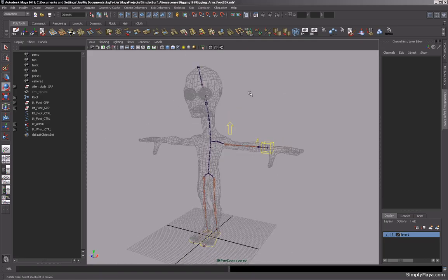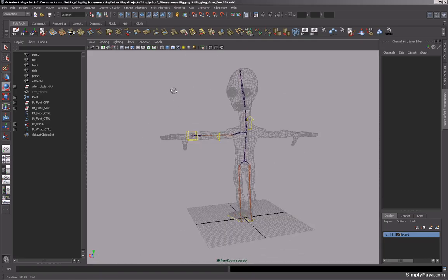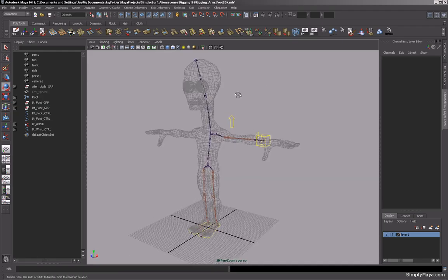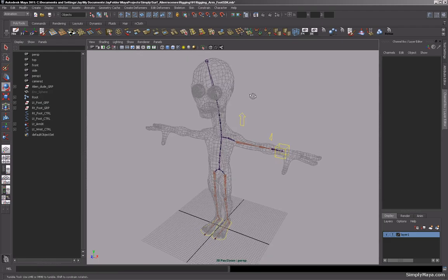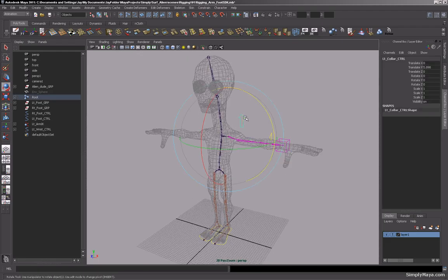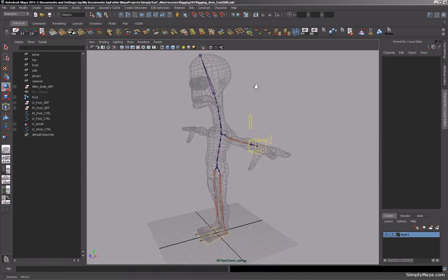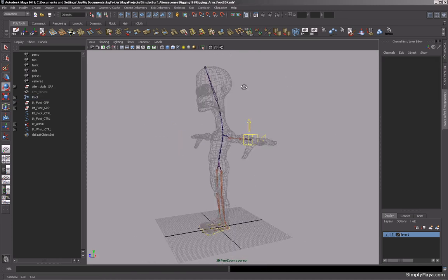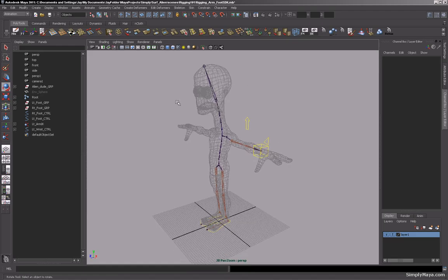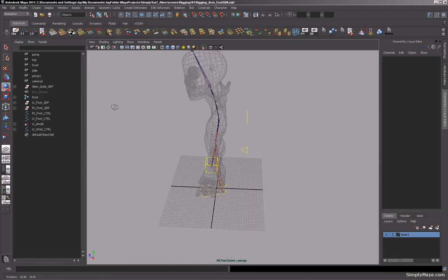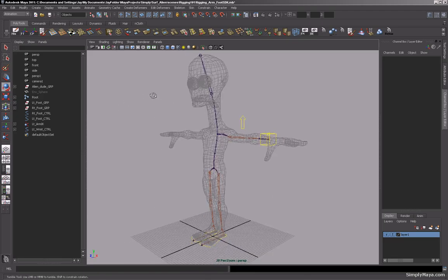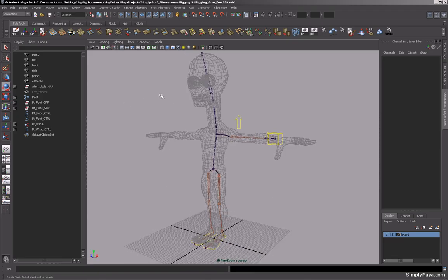So that really concludes this chapter. I hope that was alright for you. It can get a little bit fiddly, as you can see, but providing you do everything in the right order, freeze out all your transformations on stuff, you should be absolutely ready to go and start putting all these bits and pieces together. So just remember, freeze your transforms out, rename stuff, and center the pivots, etc., and you should be fine. So we'll leave that there.